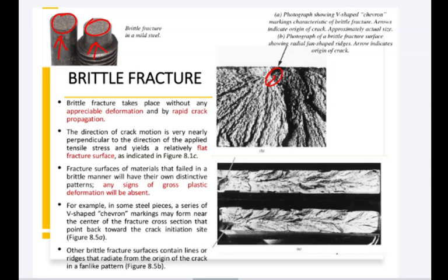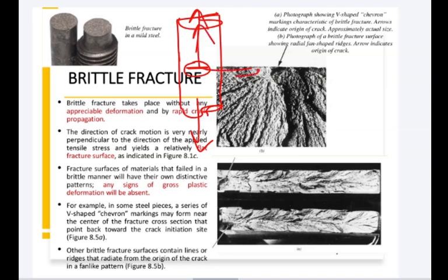Now if I have the material, look here, I will draw it here. This is, let's say, the specimen, right? And you are applying the stresses in this direction and in this direction. So let's say the crack generates here, this occurs instantly, very rapidly. But usually this crack propagates perpendicular to the applied stresses. Now the applied stress is in this direction, so perpendicular to this is this direction, right?